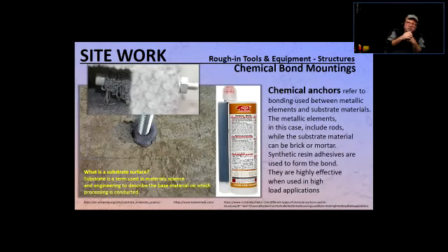I called the company who installed that. They came in and installed those brackets again, and it was about 200 brackets or so. Okay, so it was not a small job. They had to come in on their own time and pull all those brackets out and do different types of anchors. And then I came in again and I said, you know what, these new anchors are nice, but they still don't work. So they had to come in a third time. But then they did some research and decided to use those chemical anchors, and they worked. It was nice and sturdy, heavy load. So sometimes it's the go-to solution when it comes to that.